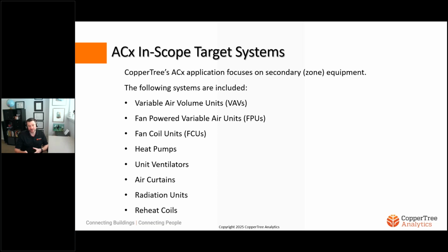What we can do though, by targeting these less critical pieces of equipment and only writing to very specific things and getting them to do things with that, is also test that primary equipment, but under real world scenarios where we can simulate load in a building or ask all the zones in a building to go to a certain temperature set point and then watch all of the equipment all the way upstream and downstream react to that. And with FDD, if it is deployed on the primary equipment during that time, we then catch the faults that we see through that.